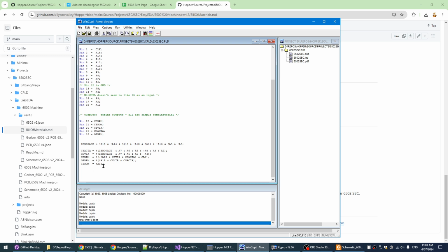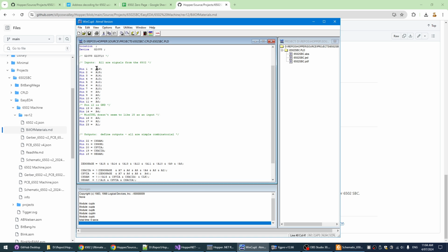ROM is just ROM and RAM. Between ROM and RAM, it's basically just address line 15: first, bottom 32K, top 32K. And then RAM I've programmed as the bottom 32K, but not the VIA and not the ACIA. RAM also has a second, well, that's the output enable for the RAM. And then the chip select includes the clock, because you want to do it on, I think, the second half of the cycle, so that the chip has long enough for the address to settle. So the clock is one of the inputs there.